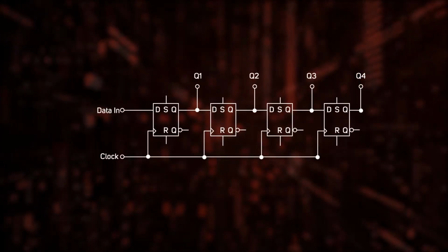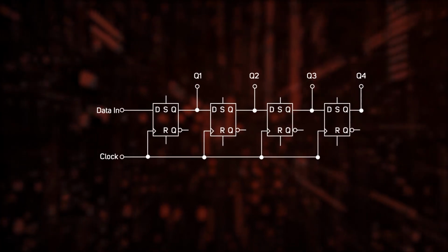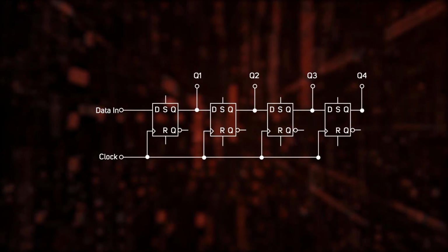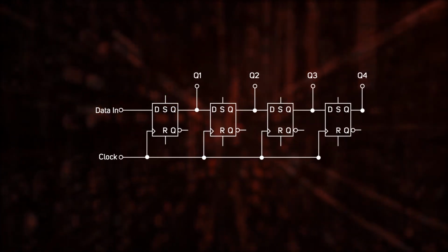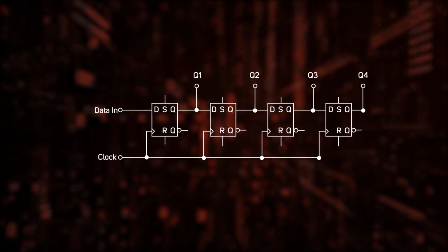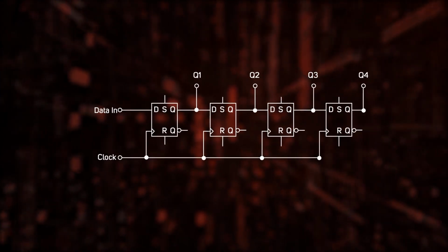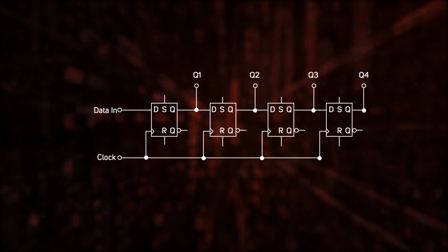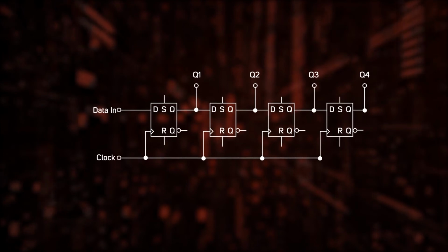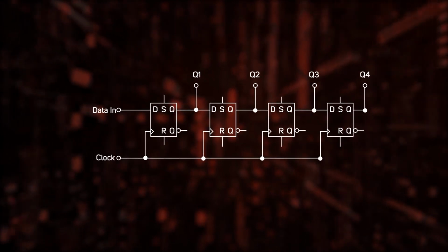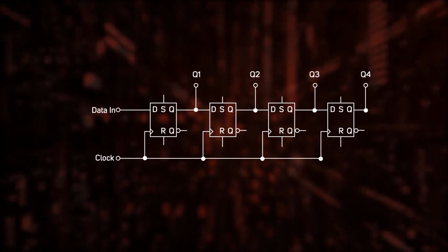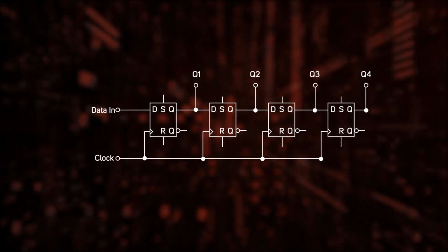Look at the diagram of the SIPO register. What difference can you make out from the SISO register? The external outputs are more in number instead of a single output. We have 4 external outputs. The input is the same as SISO, because the input mode in both the registers is the same. So, we should concentrate on the difference, how the output is produced, to know about the SIPO register better.